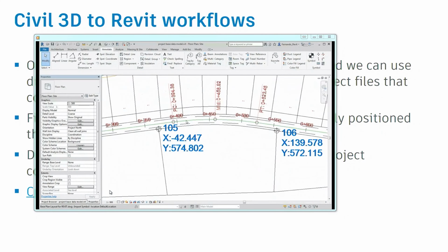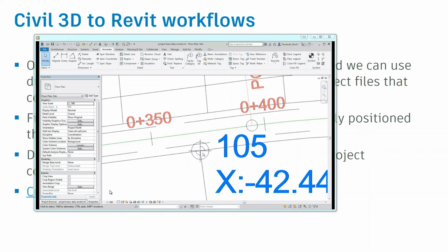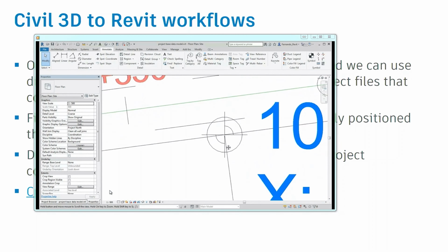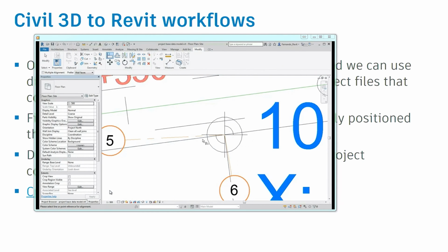So what I do, I go to my master plan file. This is my established point. I'm going to create some information here. I'm going to draw grids to create an axis, two axes. Right now, I put it manually. I'm going to line them through the property lines I have there.